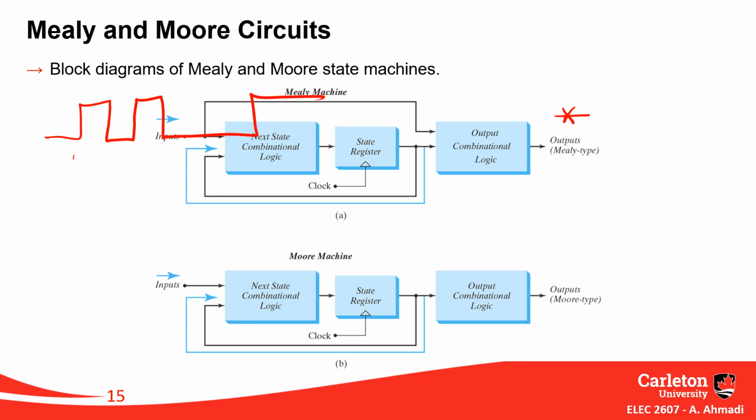But here, if you have same input to a Moore circuit, these changes of input must go through changes of states first, make some changes in the state, and your output always goes from a state which are correctly synchronized with your clock. So your clock is always applied. Doesn't let any out of clock change in your output.